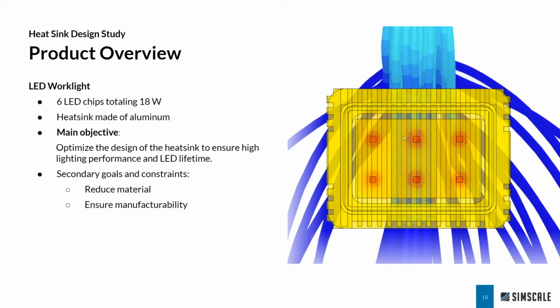The main objective of running the simulation is I take a look at a couple different heat sink patterns here, and really I'm trying to answer the design question: how many fins do I need in here to get an optimal operating temperature on the chips? Do I need more fins? Does that result in a better performance? Of course, as you add fins, your material cost and manufacturing costs, machining costs go up. So we'll understand the sort of trade-offs between those options.